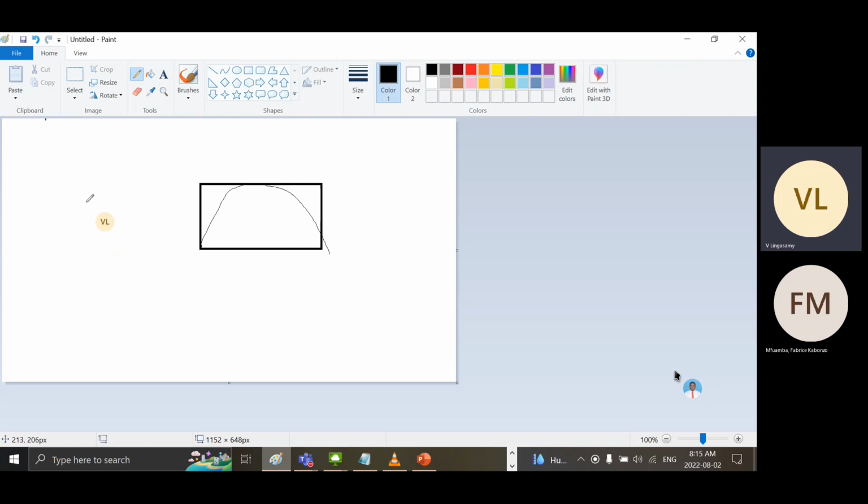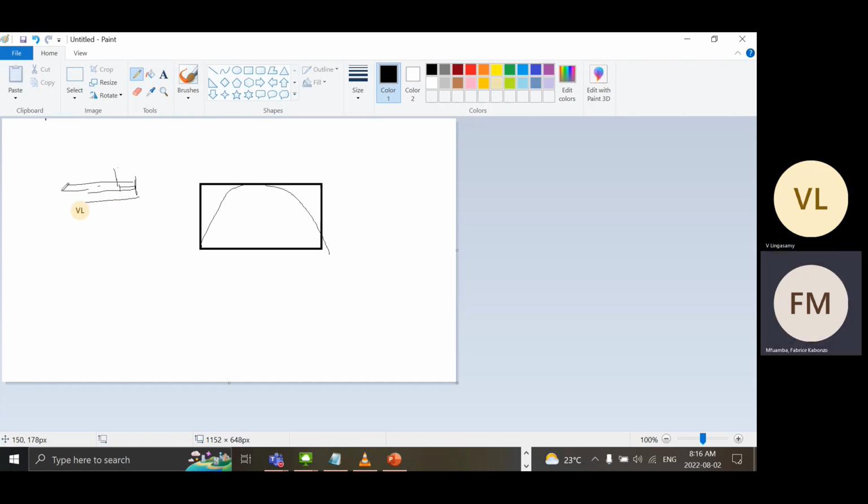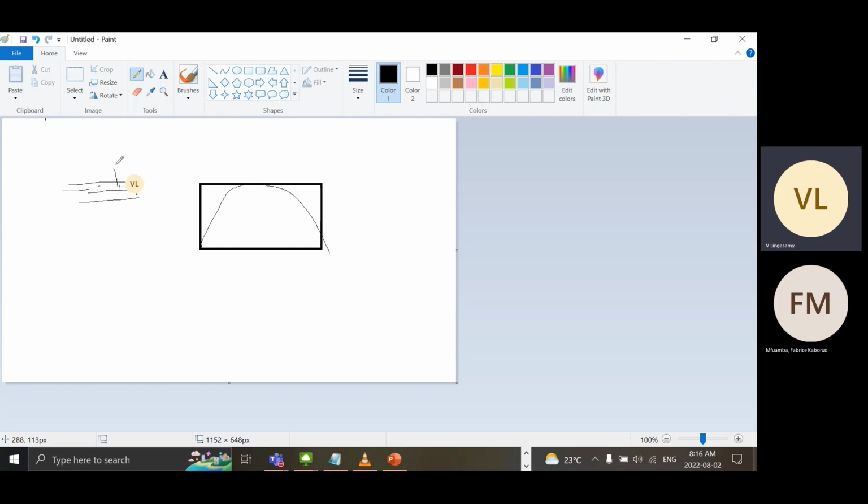So how it works is, in a waveguide, either we can use a wave port like this, or we can have a waveguide like this. In general, we'll have an SMA connector or an N-male connector like this. And here what will happen is it's actually a monopole, so it will radiate. This distance will be lambda by 4. We have to optimize this distance for bandwidth, so that 90 degree, 90 degree, this will be 180 degree, right? So that you will have a 0 degree. Then the wave will start propagating in this waveguide, basically. So that's the waveguide working principle.